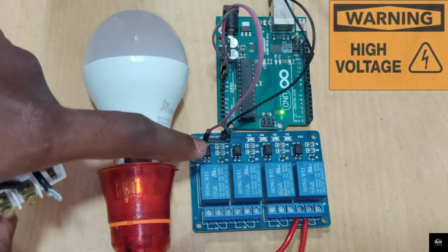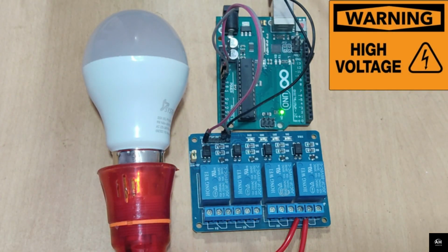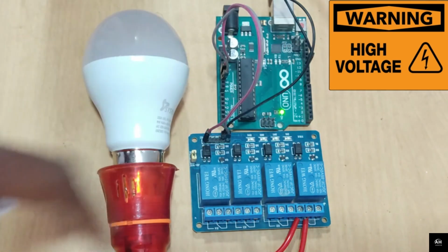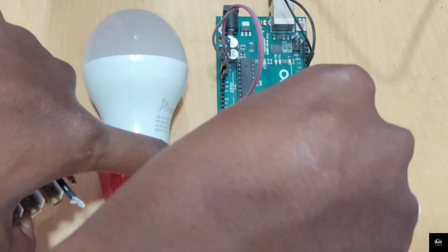So just check if you have removed the mains cable, and also turn off the switch and see if all the cables are removed, so you won't get any kind of shock. And please be extra cautious when you touch the relay module. If you have power on your main switch, it will be getting current through this relay module. So just be extra cautious about turning off the switch every time you try to connect anything to the relay module. So I've checked it twice.